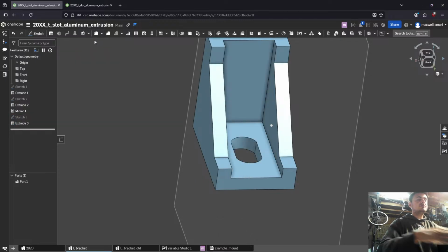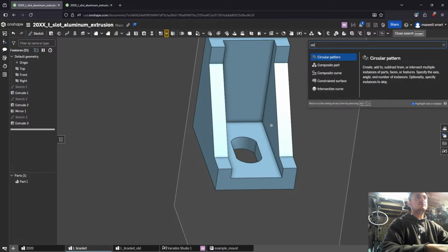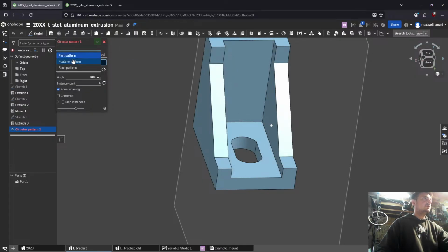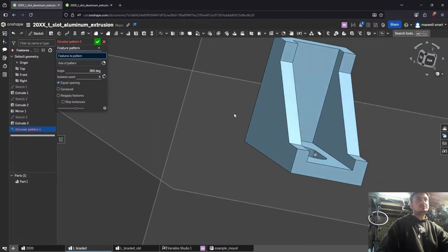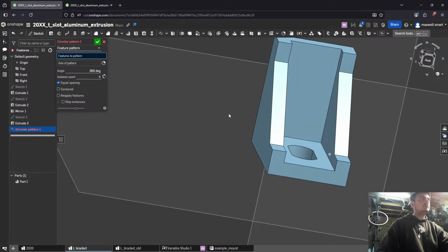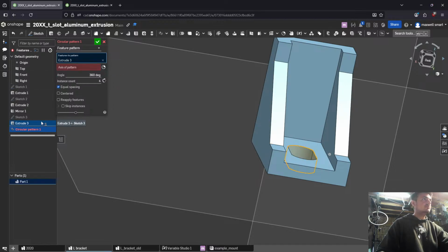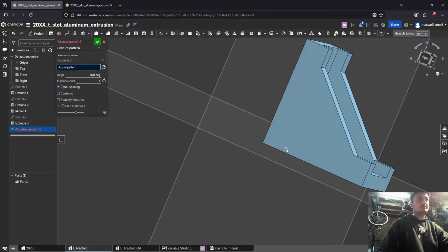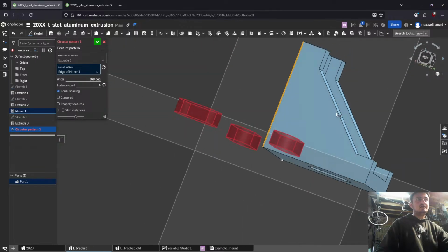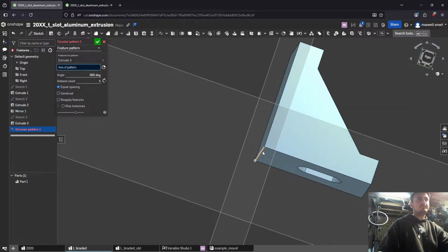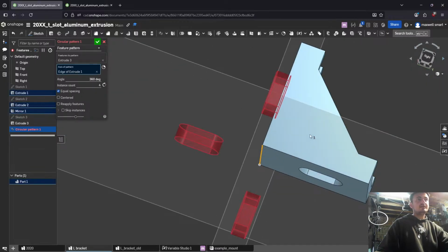And then what we want to do is a circular pattern of a feature. Oh, do we have an axis of rotation? I can probably do a make connector. The feature to pattern is this extrude. The axis to pattern... Okay, so that picks the Z. So instead of that, I want to pick this, right?